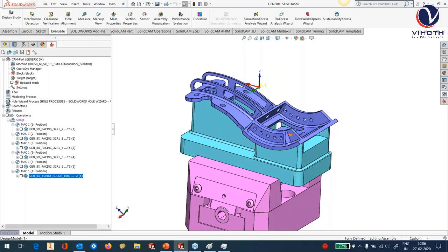You should present a couple of things. One is the ease at which you generate your toolpath. If you're going to define everything in front of the customer, or even in front of your own user, it might sound that the software is a bit difficult. But if you have your templates ready on your side, you can just keep applying templates. Over a period of, let's say, 1 year or 2 years, you would have generated several jobs in 5-axis. You could take 10, 12 of them and keep their templates ready with you. So you get an idea, you use this template, straight away apply, select the geometry, and the calculation happens.